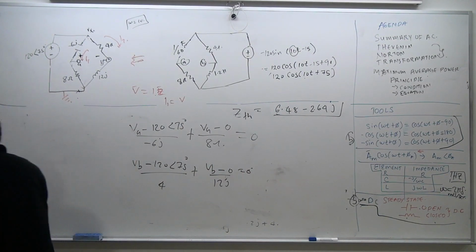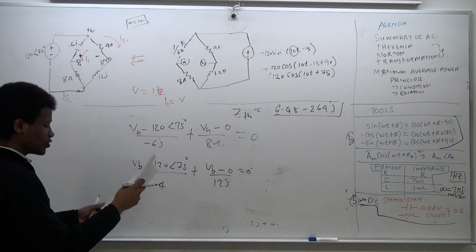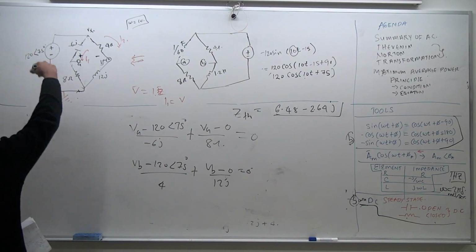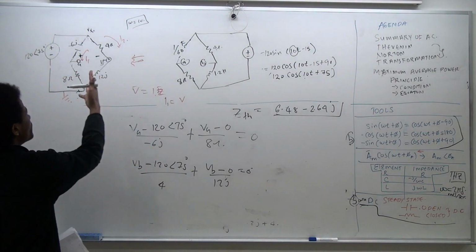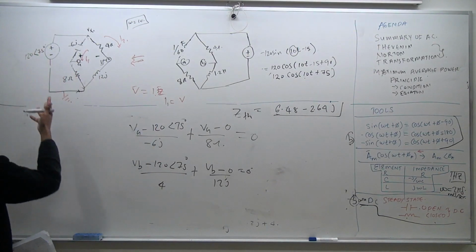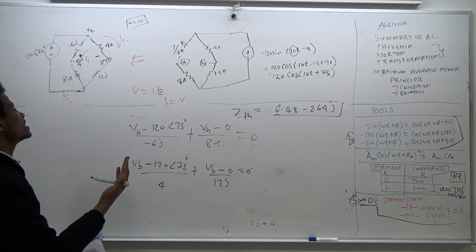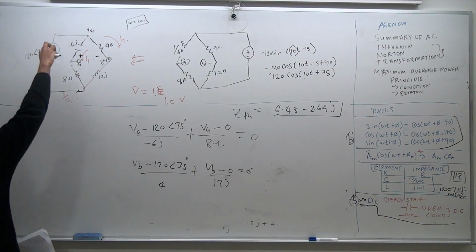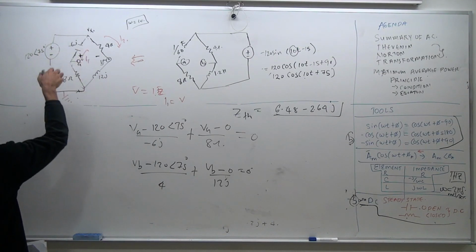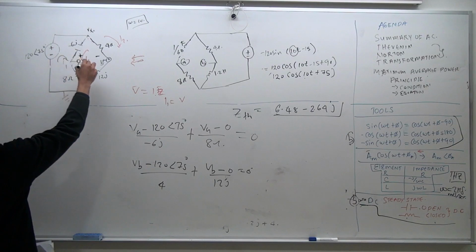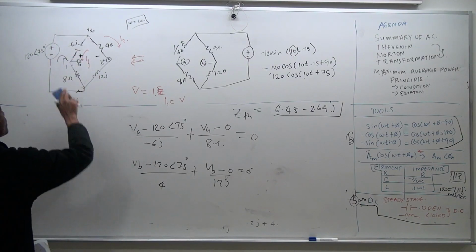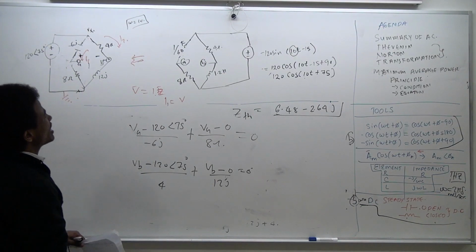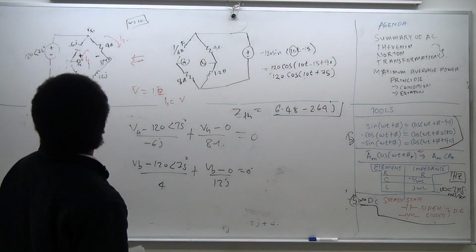Let's say now, if you apply this technique or even the technique before using Ohm's law, and there's also other techniques. You can also use mesh. In fact, mesh is actually quite convenient for this case because we have a voltage source. And mesh analysis is basically using KVL. And KVL, you talk about the voltage across a loop is 0. Hence, you have a voltage source. So it's good. You can use this voltage source and you can apply I1, for example, apply I2, and you can do the same thing. At least for I1, you could do it minus I2. Yeah, you could do it under, is it possible? Actually, I don't know. In this case, is it possible?